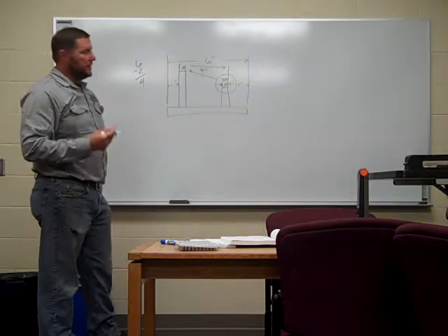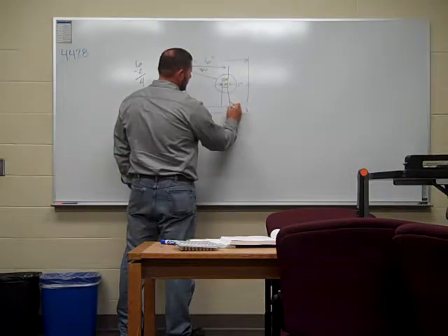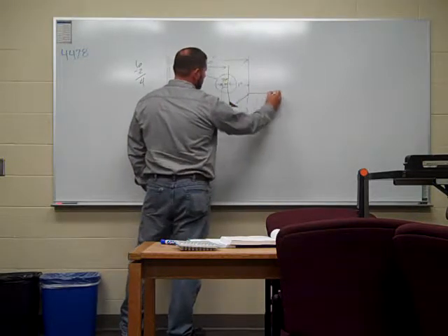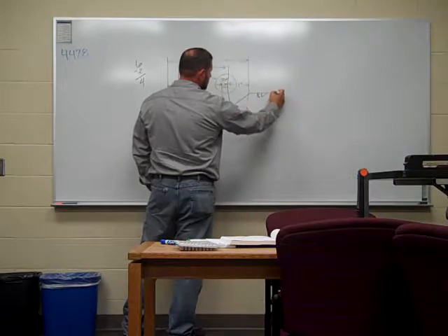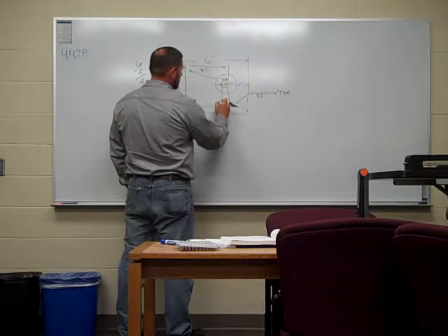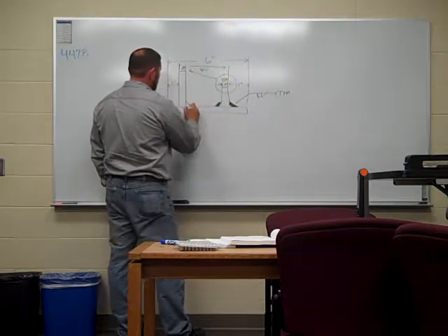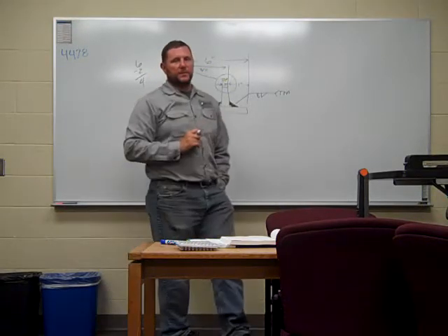You can use it in weld joints too. If we have a 1/4 inch fillet weld here on the side, 1/4 inch, might be typical. That means there's a 1/4 inch fillet weld here, 1/4 inch fillet weld here, and here. That's what that word typical means.